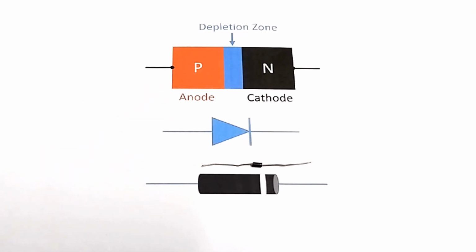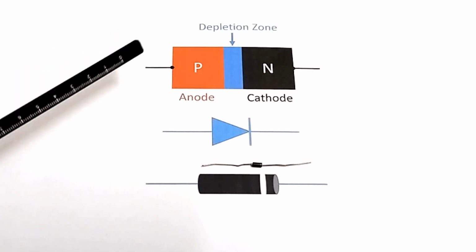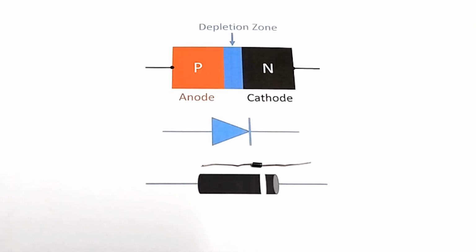And when a diode is forward biased, these are silicon diodes. When silicon diodes are forward biased, there will be a voltage across them of 0.7 volt. Usually for a silicon diode it will be 0.7 volt, and for germanium diodes, which are seldom seen nowadays, it will be 0.3 volts. So this is what we are going to measure using a multimeter in the diode testing mode. There is a selector switch which will select diode testing.